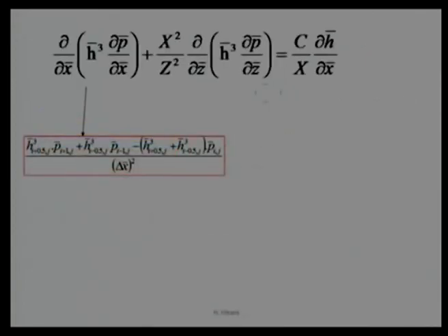Now, we have 3 terms in the Reynolds equation, which is a steady state Reynolds equation with a number of assumptions. The first term can be represented here, h is only one gradient, so we will take the half node. Calculating h at the half node is not a problem. H is a geometry, which is well defined to us. While pressure will be the second gradient, so that is why it is coming p I plus 1 j, again with the film thickness at the half node, minus, sorry, I minus half node, and pressure will be p I minus 1.